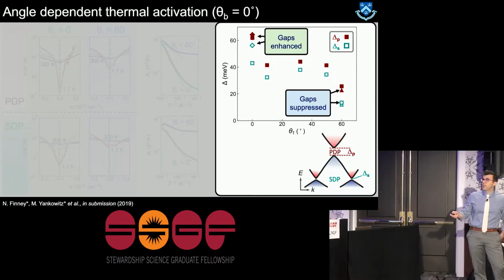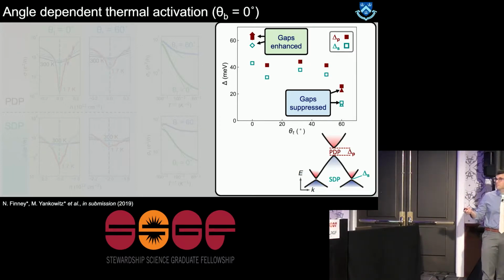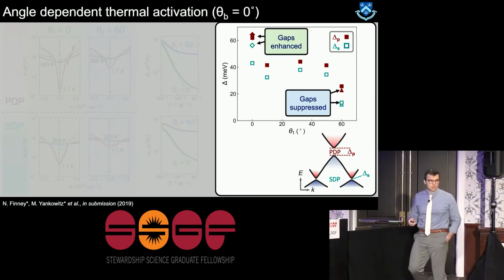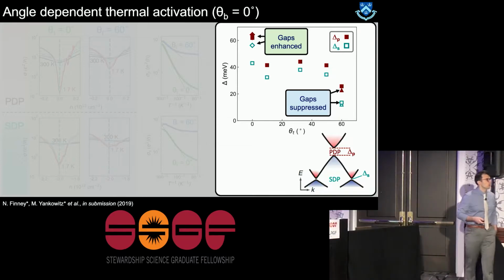I'll just quickly point out that this gap in monolayer graphene is a record gap for pristinely produced graphene moire superlattices. This is actually 60 meV, I think, which is in the far infrared regime. So this device is sensitive to the types of light signals that might come out of the center of galaxies or human bodies.